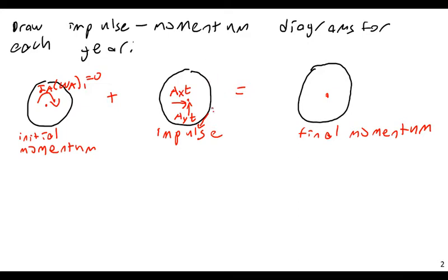I'll just call that force F, times T. In the end, this will equal IA, the moment of inertia of disk A, times the angular velocity of A, omega A, at time 2. We don't know that yet, but we'll figure that out in a second.